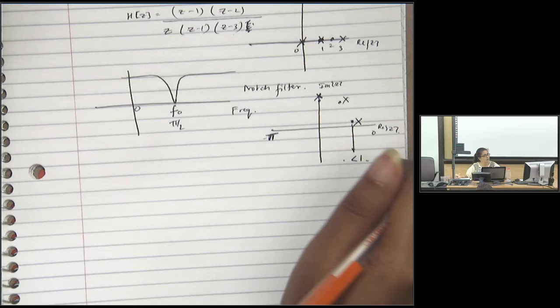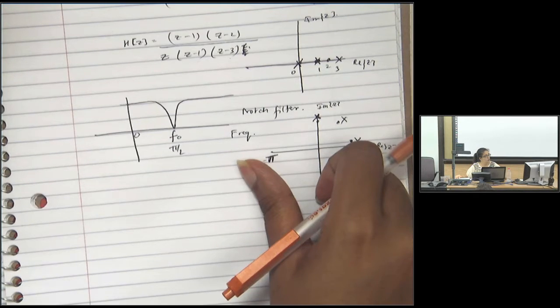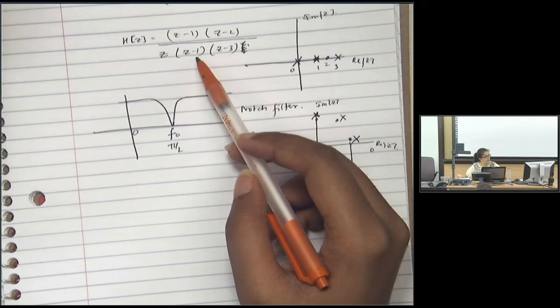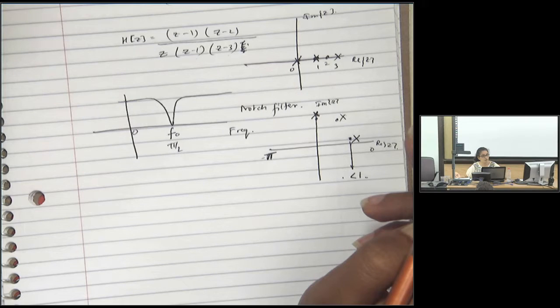When you were asked to find stability, BIBO or asymptotic, in a question like this where it cancels, what do you do then? You can assume, like you've done in the homework, that the denominator is the characteristic equation. This way it affects both the BIBO and the asymptotic.